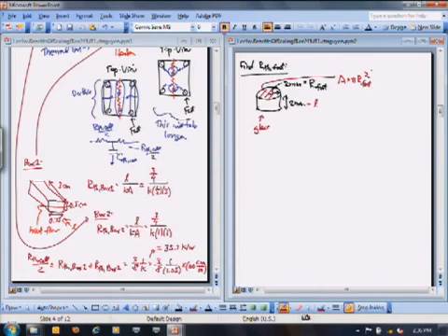So in the end, we can determine the thermal resistance of a foot fairly quickly. That's going to be L foot divided by K divided by the area of the foot. I guess I should put foot under that. And so L of the foot is 2 millimeters divided by K, still glass, so 1.05 watt per meter Kelvin, times pi, times another 2 millimeters squared here. Of course, that 2 millimeter cancels with the square from that. And you can do the simple calculation. This ends up being 151.6 Kelvin per watt.